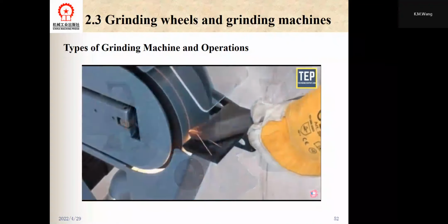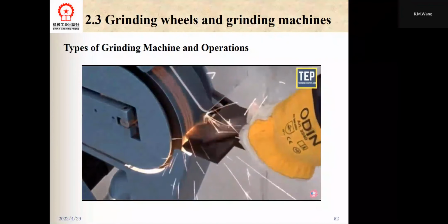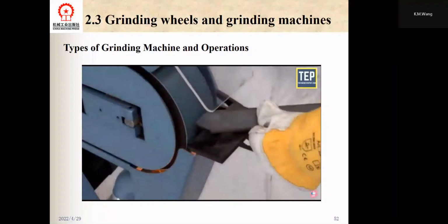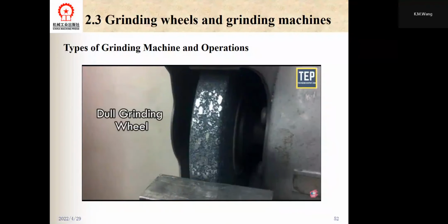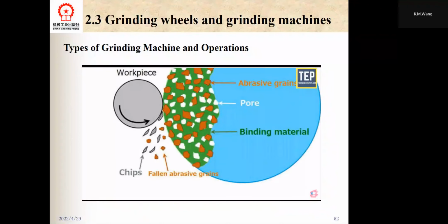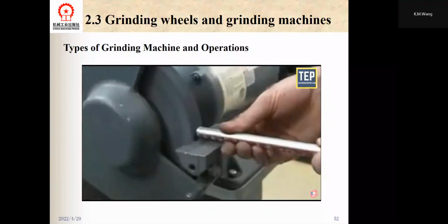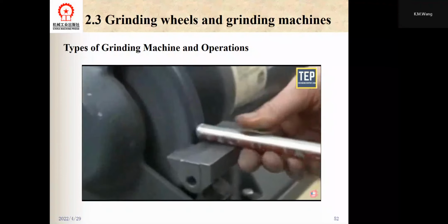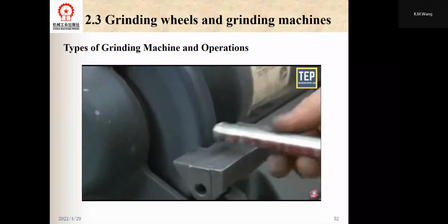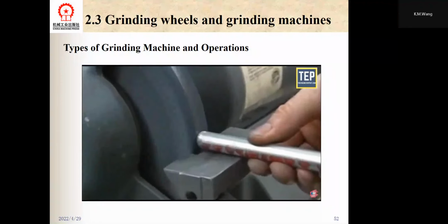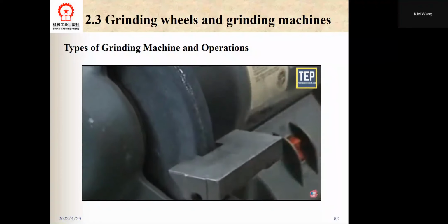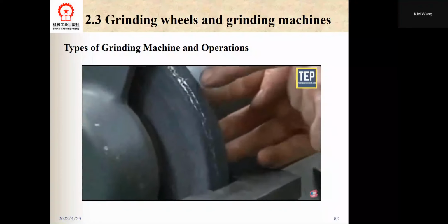When a grinding wheel is applied to the workpiece, the sharp edges of the abrasive grains, after a certain amount of time, will lose their cutting effect and become dull. At that stage, the abrasive grains should either split to form new edges, or break away from the wheel, exposing the next layer of grains to do work. If the dulled grains stay in the wheel, they simply keep on rubbing on the work without actually cutting. This defect is known as glazing. If, on the other hand, the abrasive grains break away from the wheel too early, it causes a reduction in the life of the grinding wheel.